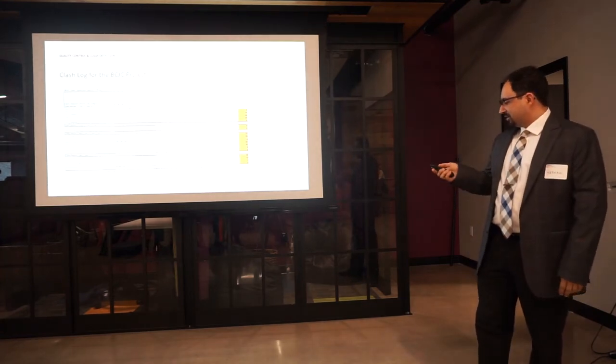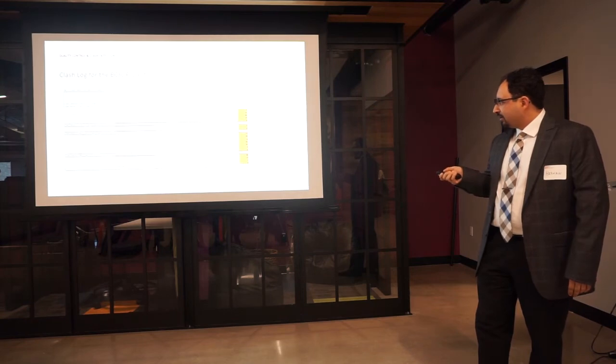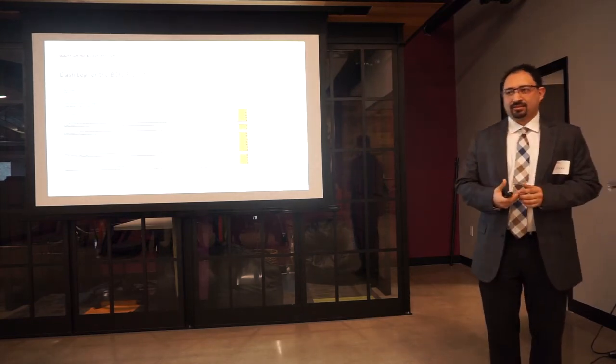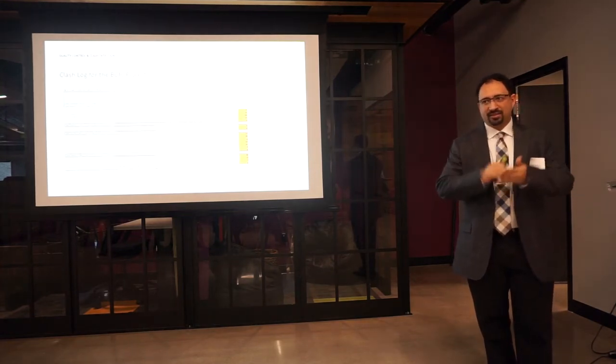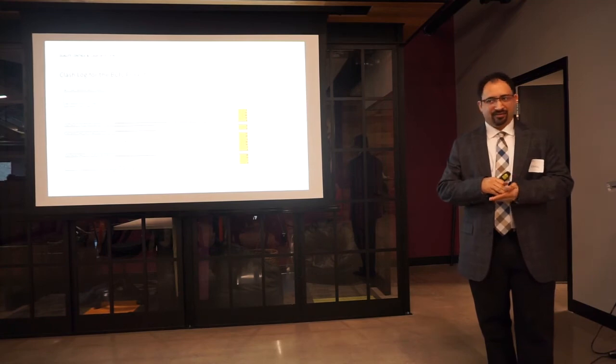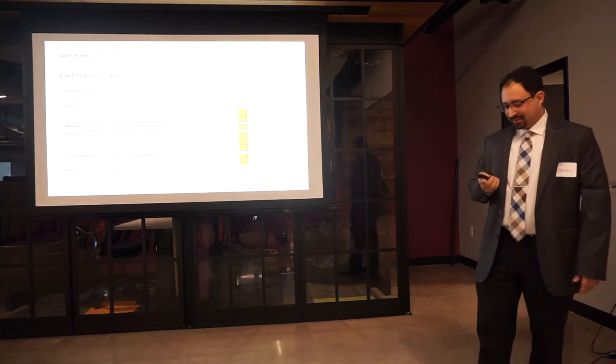It also allowed us to find, as I mentioned before, our 1 hour rated walls versus our MEP, and that let us identify a nice list for the contractor. This is what you need to fire caulk. And of course, if you add anything, you add it.